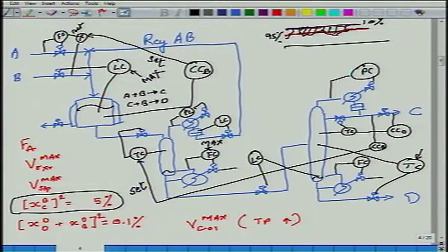In the reactor, right? So if this level is going down, that means I need to jack up the generation rate, the reaction rate inside the reactor. By the way, of course, this will be temperature control, that's obvious, right? Yes or no? So, in the second column, we are using temperature control twice.